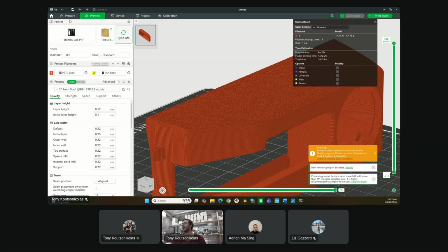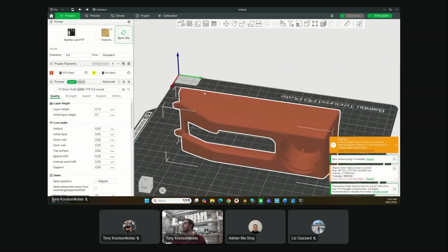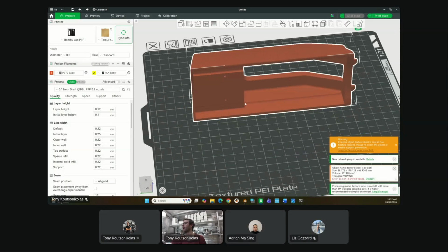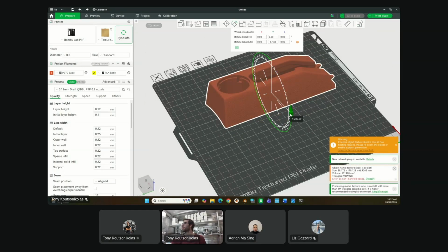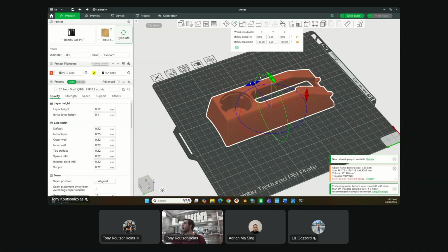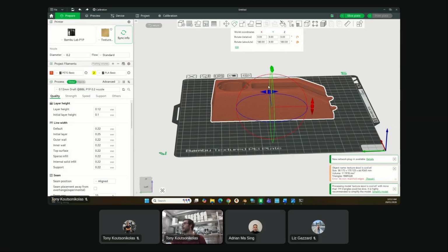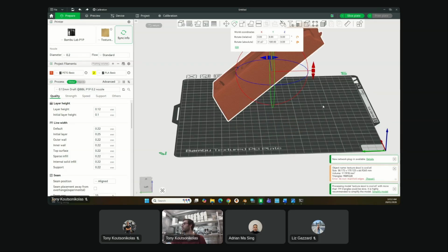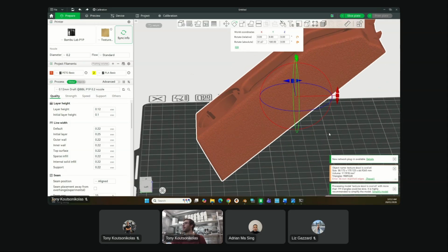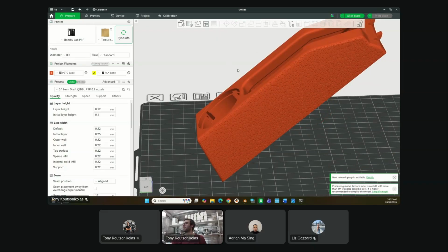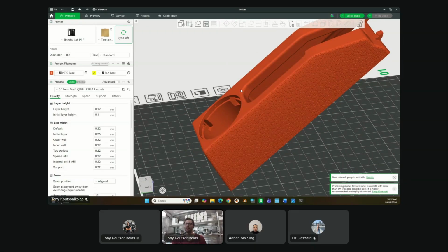Or here's the other alternative. You kind of get the best of both worlds if you angle the part and it's all uniform. So let me try and make this right. If I do it like this and print it like that, then say this top surface, I know it doesn't have a texture on it, but where my mouse is now, if that had a texture on it, it will print pretty similar to this side one, because it's on a 45-degree angle to the XY plane. So I would consider printing it like that.